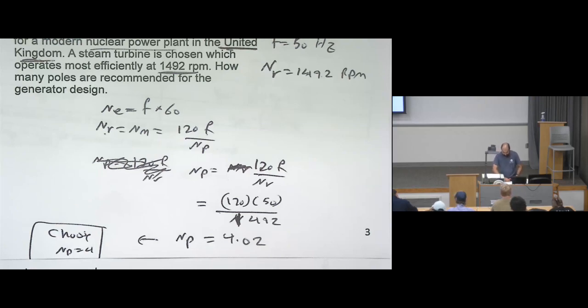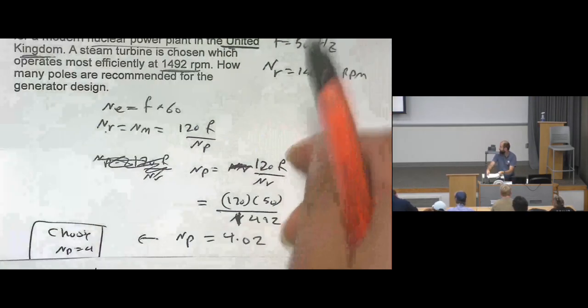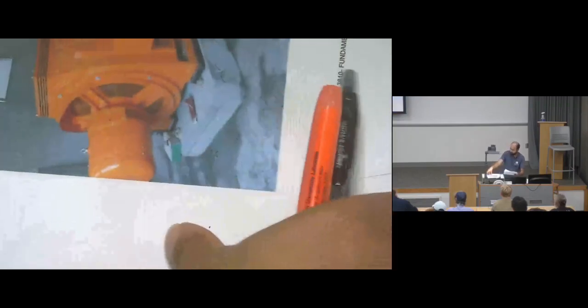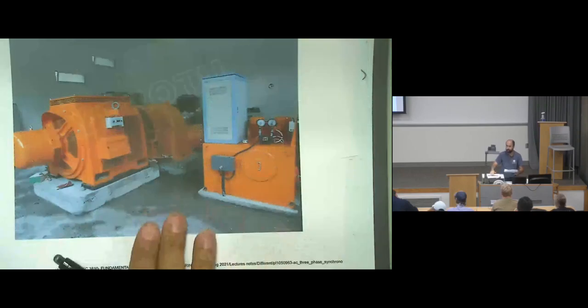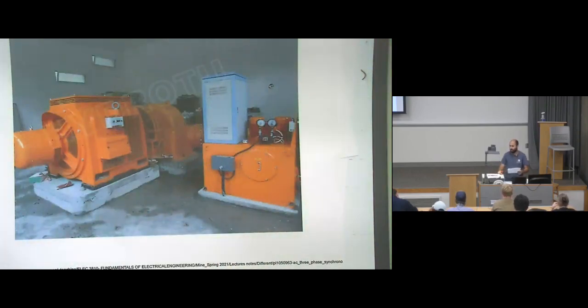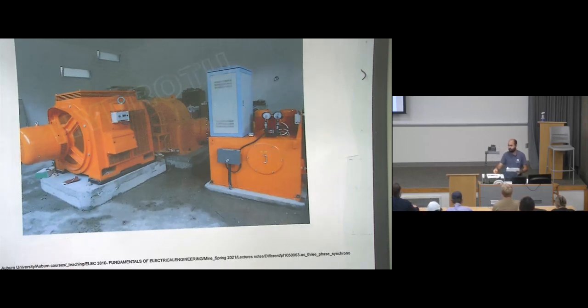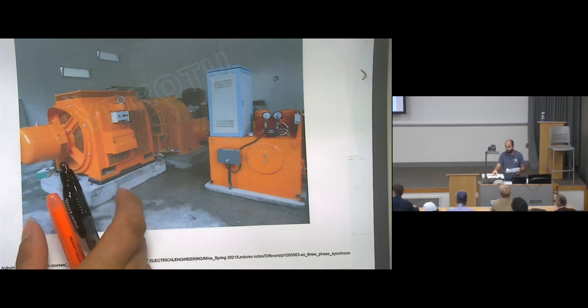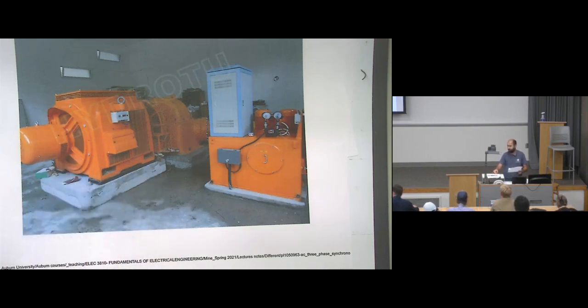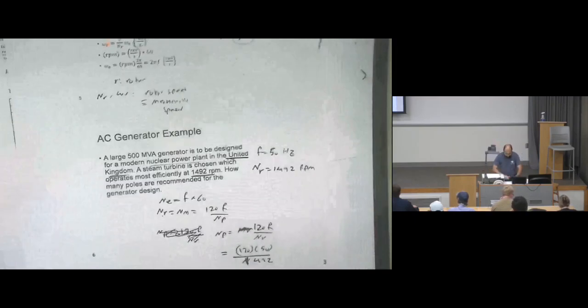Now, let's talk about this again. We need to convert this to take only the electrical parts. How can we model this motor? This is a 3-phase motor, so basically this will be converted from this. We'll first draw the equivalent circuit for the motor. Then that equivalent circuit, the 3-phase equivalent circuit, will be converted from 3-phase to single phase by assuming it's a balanced system. So we will assume the operation at balanced operation.